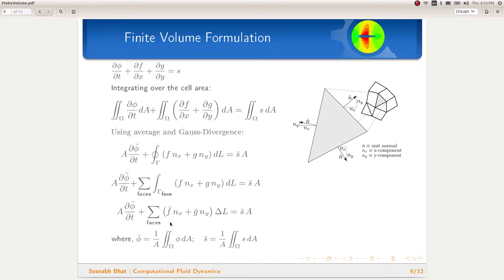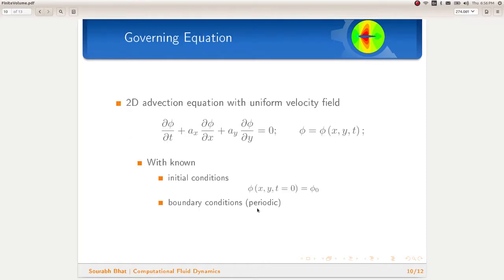Hereafter, the steps of finite volume method depend on the scheme used for calculation of fluxes and time integration. We will look at the methodology for calculation of flux terms in case of a unstructured mesh later when we deal with unstructured mesh. However, for a Cartesian mesh, as we will see soon, these terms simplify even further to give us equations very similar to the one-dimensional formula for which we have already written a program earlier. That was the finite volume method. Now, let us use it to solve our problem at hand.